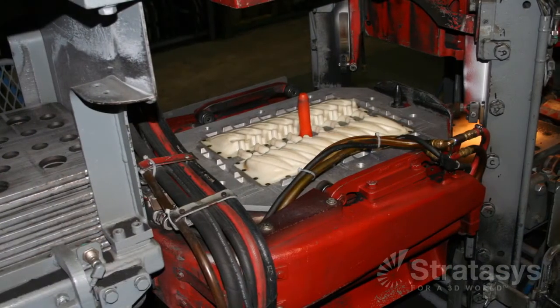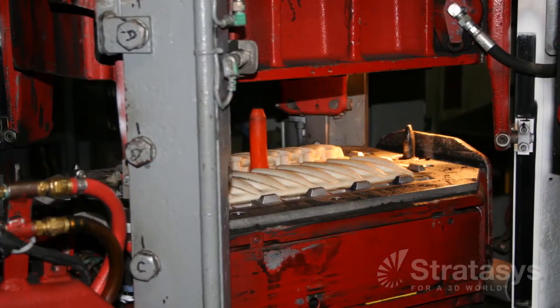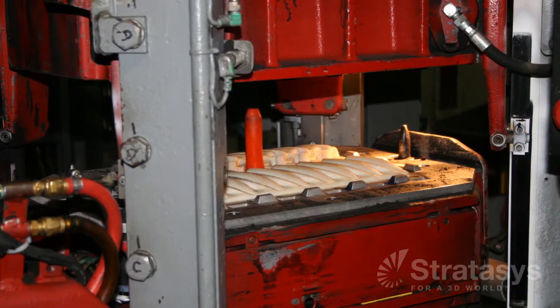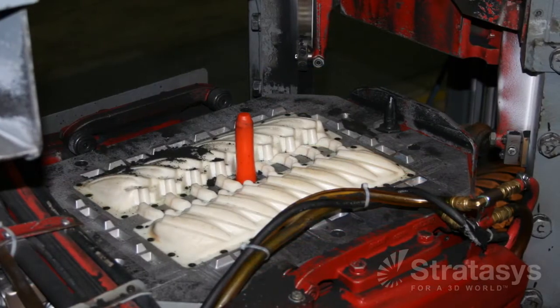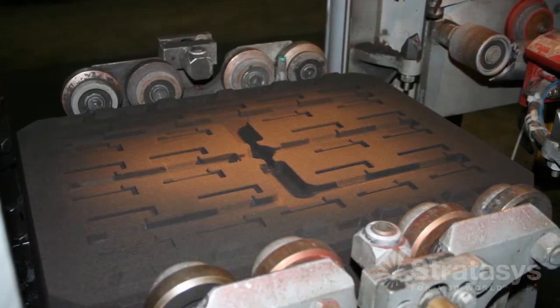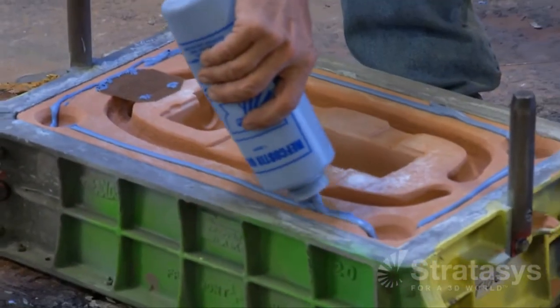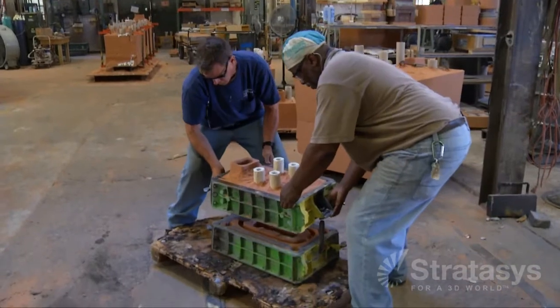With FDM's real thermoplastics, the patterns are robust enough to withstand the sand abrasion and the compaction pressures when forming the sand molds for any of the methods. Loose pattern sandcasting with hand ramming forces for no-bake sandcasting, and match plate inserts for green sandcasting. Once the sand has been formed around the pattern to create a cope and drag, the sand molds are ready for metal casting.